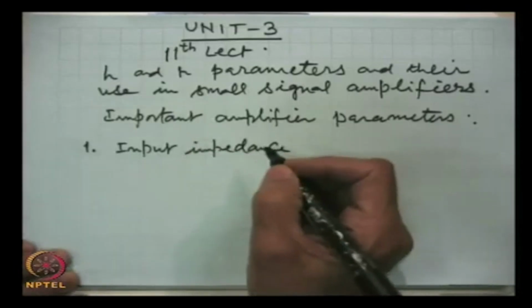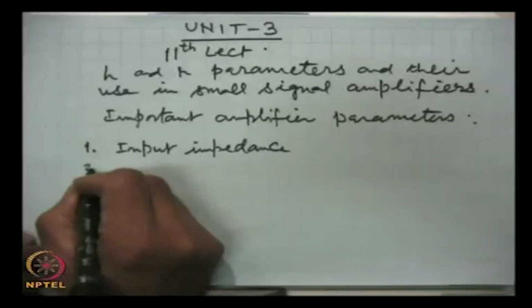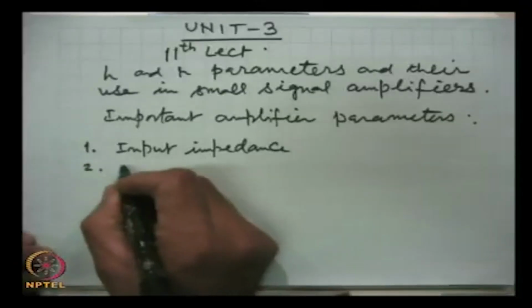You know that resistance and impedance may differ at high frequencies. When the frequencies are small, resistance and impedance are very close to each other, and so we may call it input resistance or input impedance, but it is better to call it input impedance because we are not yet defining frequency. The other parameter is the voltage gain.